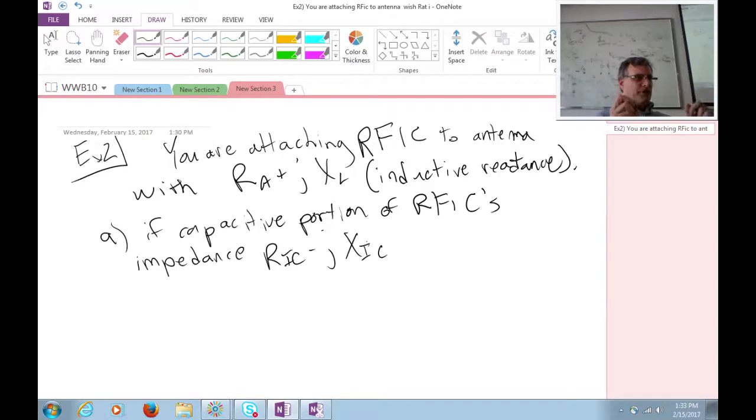RF, that's almost impossible to work with, because if you go high enough in frequency, these tiny little wires they use to bond the pins of the package to the actual chip interconnects are like really high inductors. They're so thin. The thinner a wire gets, the more its per unit length inductance increases, because the current gets concentrated down into such a small pipe. And that tends to wreak havoc on RF. Anyway, back to our problem at hand.